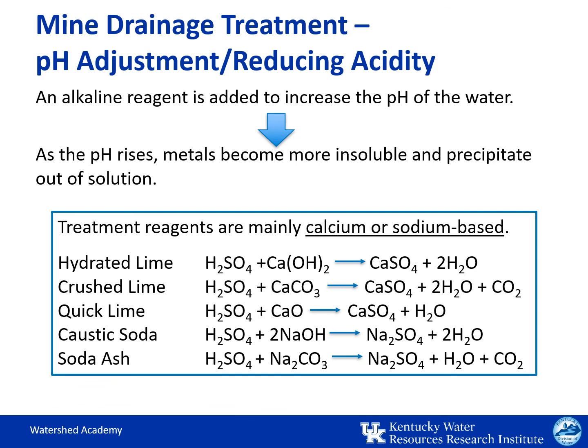Crushed limestone, calcium carbonate, is the cheapest reagent by weight, but has limited solubility and lower reactivity at higher pHs. Since it is unable to raise the pH much above 7.5, it is inadequate to assist with the precipitation of most heavy metals. However, passive treatment systems have successfully used covered limestone drainage trenches to treat acid mine drainage in an anoxic state.